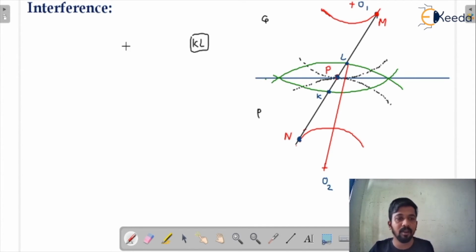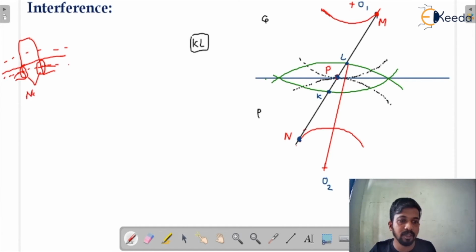We have seen in the tooth profile diagram that there is the pitch circle, the base circle and the addendum circle like that here. The portion of the gear or pinion below the base circle is considered the non-involute portion. Yes or no? This is the non-involute portion.